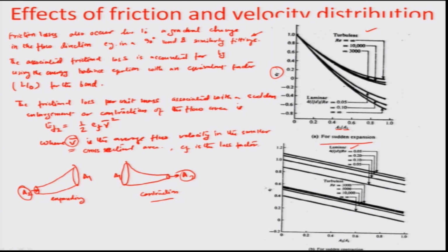And the way that you look at EF is plotted right here, and these are two very important trends borrowed from elementary fluid mechanics, where we talk about the energy loss because of bending or contraction as a function of the area ratio.